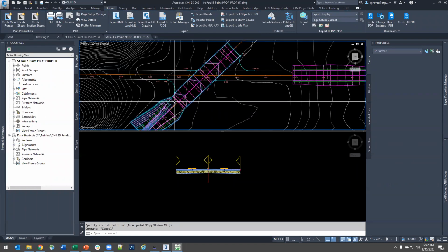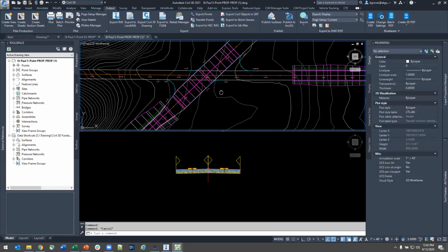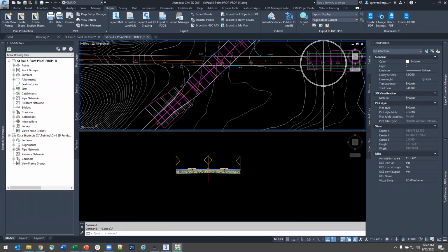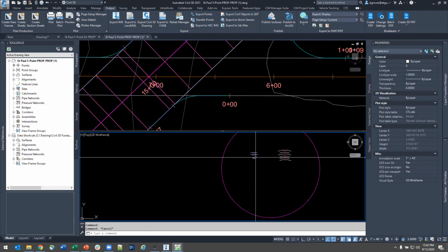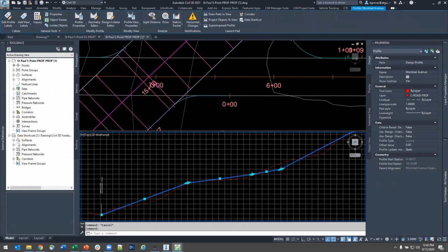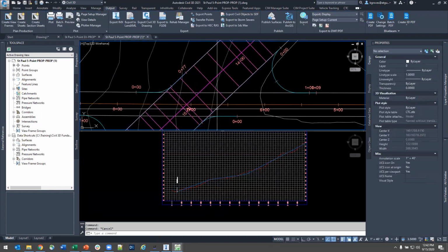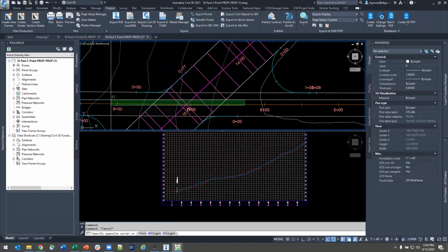I'm also going to turn my surface off because it's going to look really goofy with all these disconnected segments. So that's my main area. I've got my full road coming in and out on both sections. I have my lane only going through on the side over here, but I also need to make sure that my profile is appropriately locked wherever it's finding all of these different things. So this is where the intersection wizard is going to come into play, so that Montreal Street running east-west here is going to actually tie in and do so dynamically.